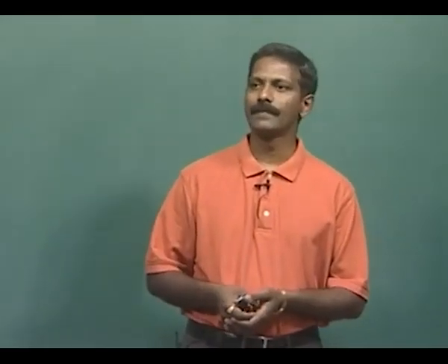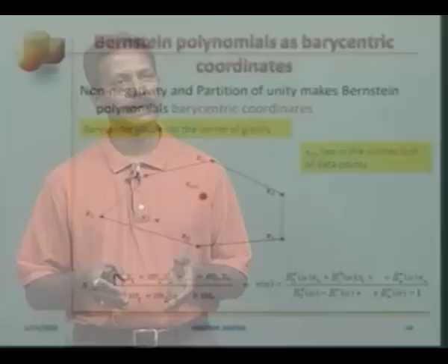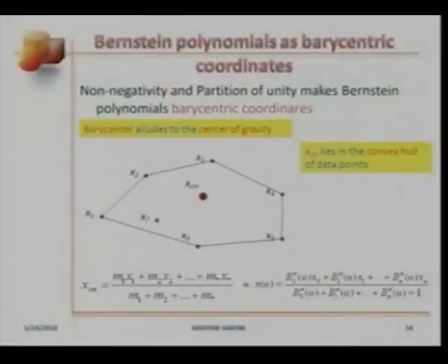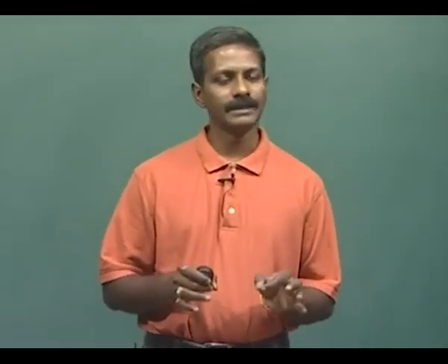We had considered an example to see how barycentricity played a very vital role in designing Bezier curves. An important thing, any point on the Bezier curve is bound to lie within the convex hull defined by the corresponding design points, and this was the essence behind the Bezier curve models.